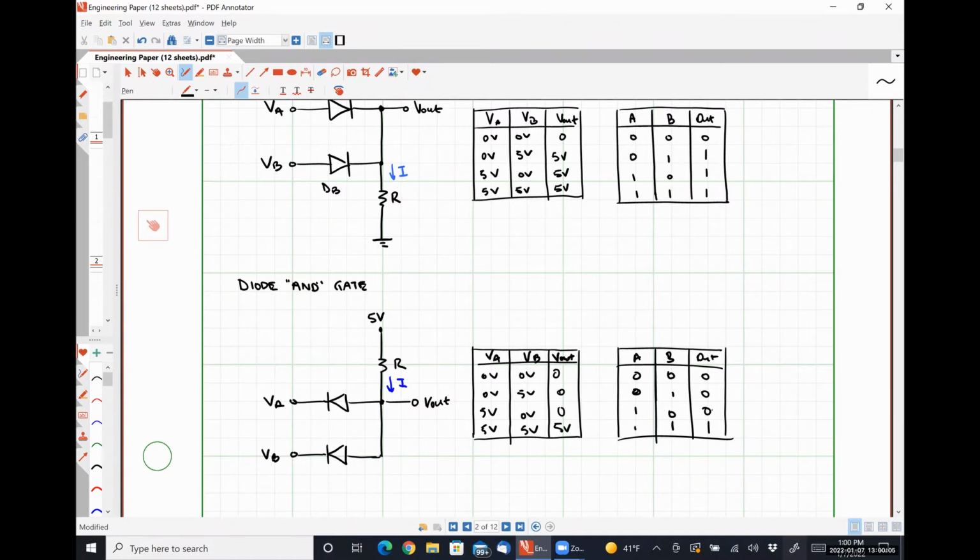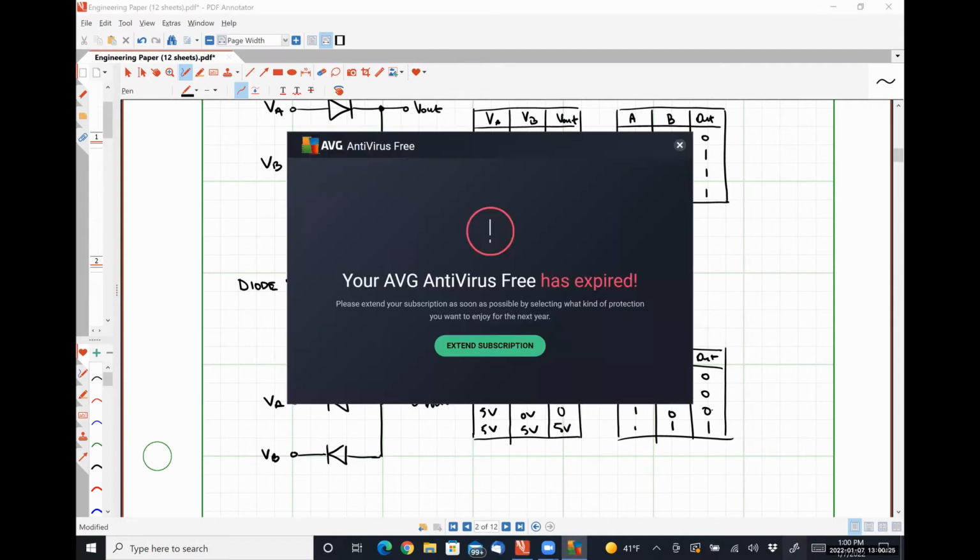One of the biggest issues with using diode logic gates like ANDs and ORs is that you can really only have one stage of logic, because for a real diode where it's roughly 0.7 volts to turn things on or off, if you chain 1 or 2 stages together, you'll see that your output voltage is falling.